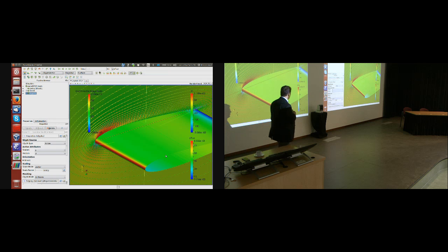Okay, the third thing that I want to do is I want to visualize the pressure gradient. How am I going to do that? Okay, so part of you probably has got a button saying give me a field and then calculate the gradient and show me that, but I don't want that one. I want my gradient to be consistent with the way that I'm working in discretization. Okay? And there is quite a lot of things like that that I want to do, and in older versions of foam we had little executables for each one. So magnitude of the velocity, or Q criterion, or entropy, or gradient, or magnitude of gradient, divergence of the flux, blah, blah, blah.